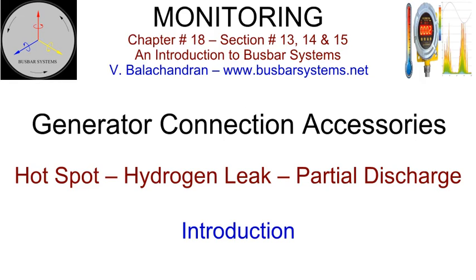Introduction. Generator connections are expected to be extremely reliable. Routine maintenance is carried out during planned shutdown of the unit. However, there is a need to monitor a few parameters in critical areas, such as hotspot temperature, hydrogen leak, and partial discharge, among others, to undertake preventive maintenance at an appropriate time.